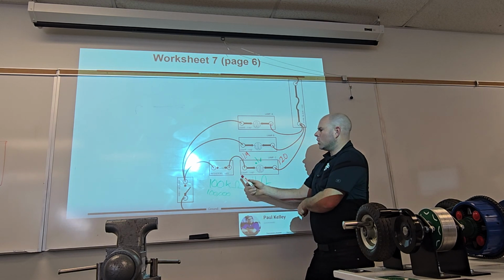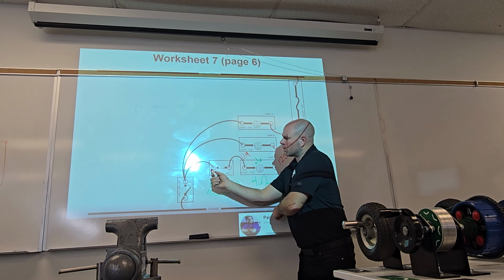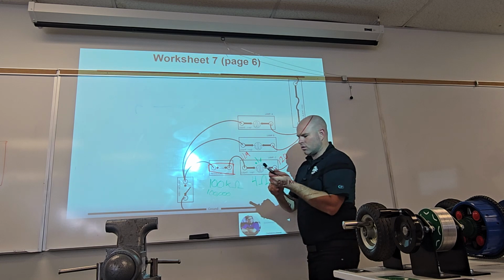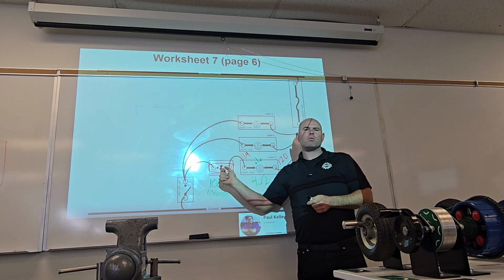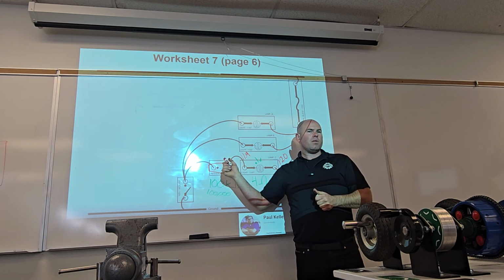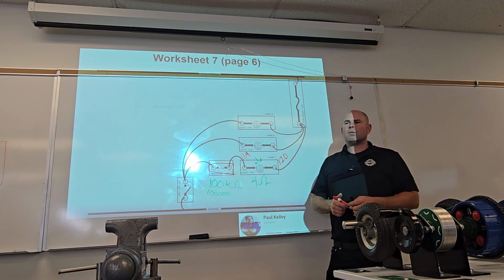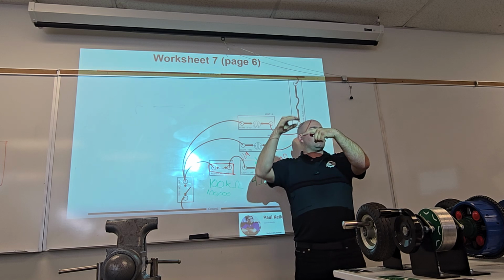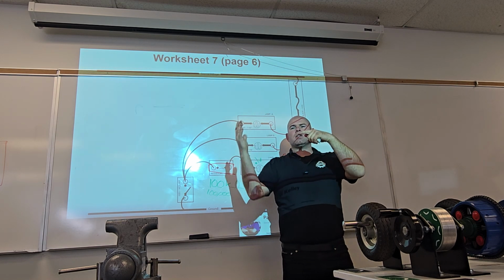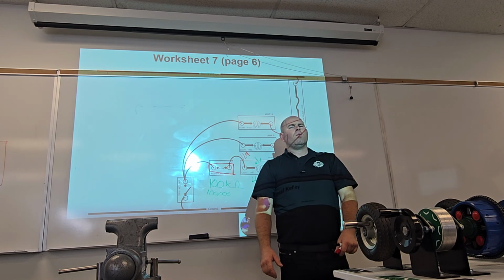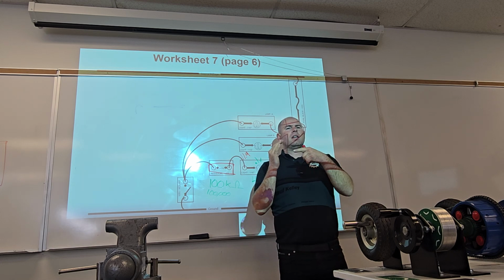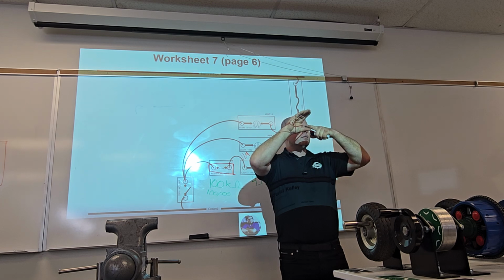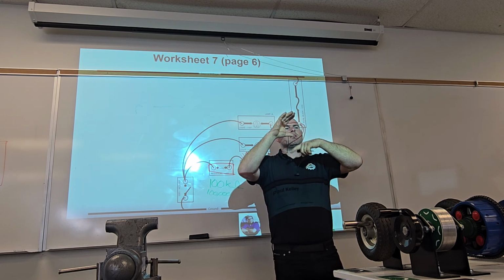0, exactly. So if I were to measure 11.9 here and 0 here, I'd be like, oh, there's a big voltage drop right in between these two. I would know that there's unwanted resistance in there. Make sense? And then whatever that component is, I'd have to replace it. So if it was a male-female connector, and I had 11.9 go in the connector and 0 coming out, I'd be like, whoa, why do I have almost a 12-volt drop on a connector? I should never have a 12-volt drop on a connector. That basically means there's almost no connection between the two.